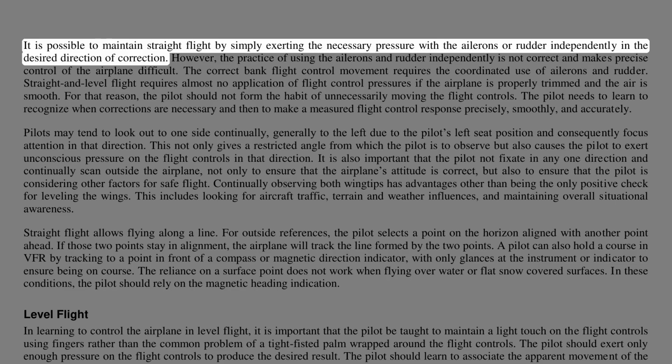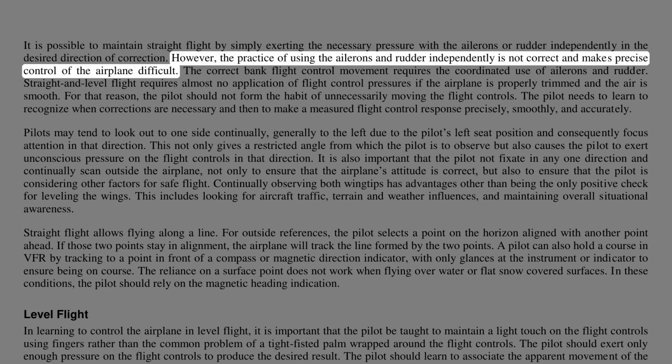It is possible to maintain straight flight by simply exerting the necessary pressure with the ailerons or rudder independently in the desired direction of correction. However, the practice of using the ailerons and rudder independently is not correct and makes precise control of the airplane difficult.